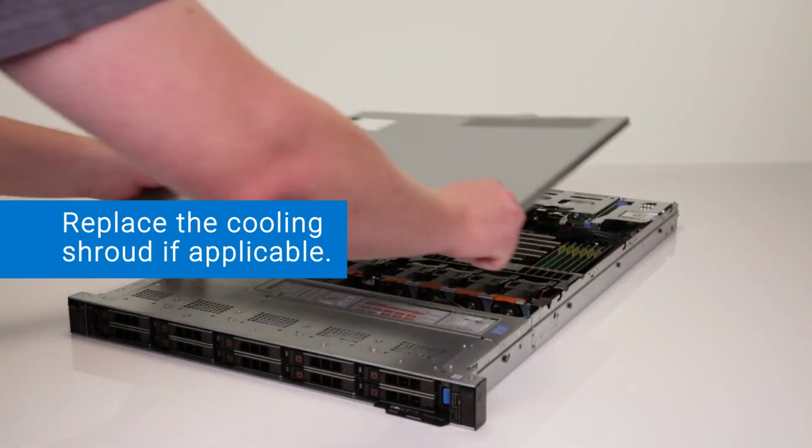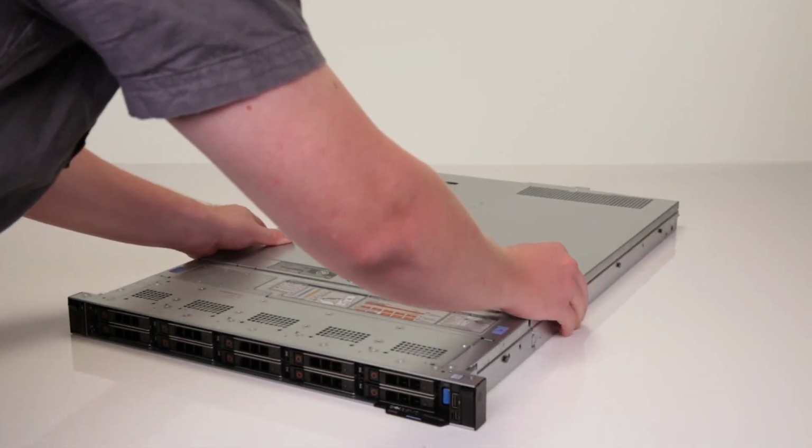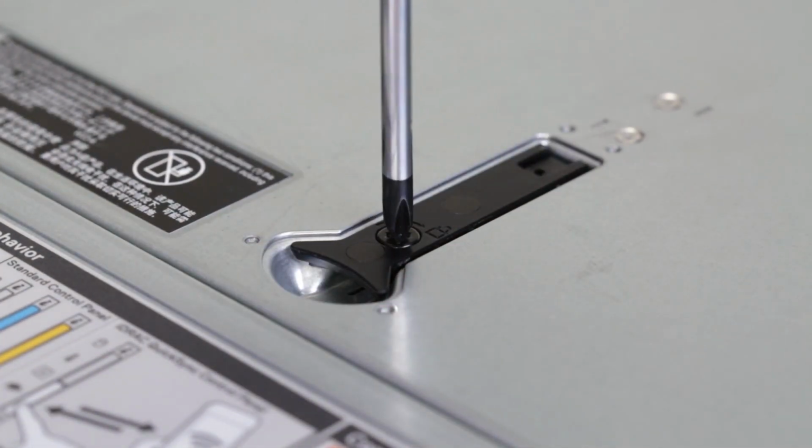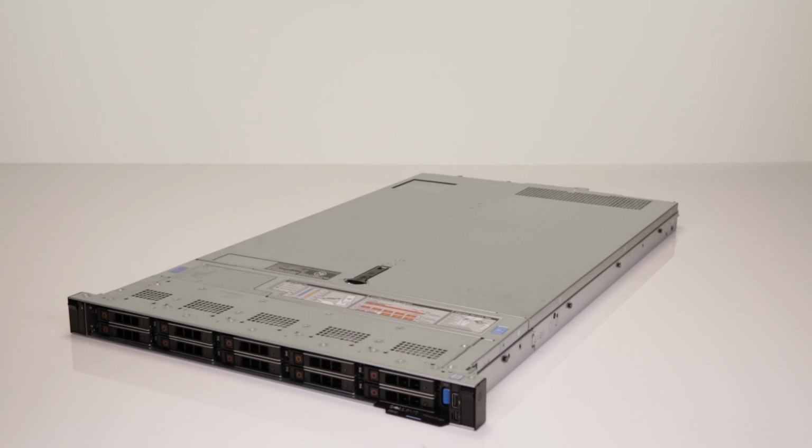Align the slots on the system cover with the tabs on the chassis. Lower the latch to engage the cover onto the system. Then, rotate the latch to the locked position. Reconnect all the cables and power up the host.